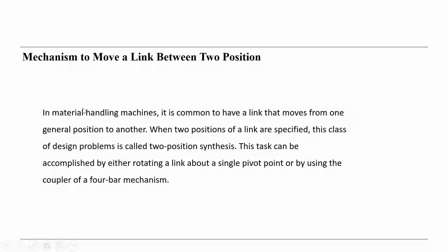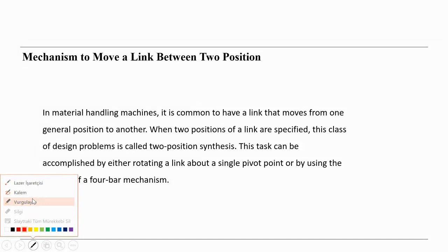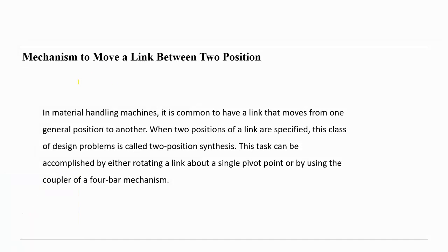With the synthesis, another issue we are going to discuss is a mechanism to move a link between two positions. Two positions are given, and we have to design the mechanism in order to realize these two positions. Especially in material handling mechanisms, it is common to have a link that moves from one general position to another, that means from one position to the other position.